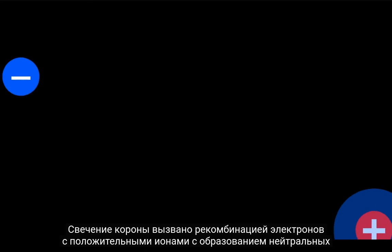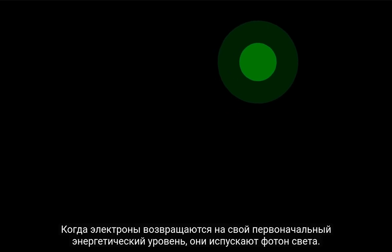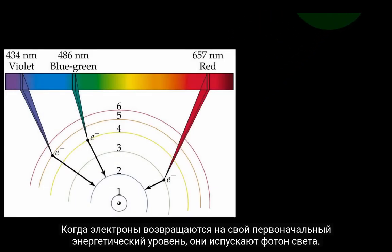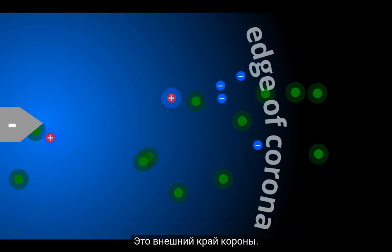The glow of the corona is caused by electrons recombining with positive ions to form neutral atoms. When electrons fall back to their original energy level, it releases a photon of light. At a certain distance from the electrode, the electric field becomes low enough that it no longer imparts enough energy to the electrons to ionize the atoms as they collide. This is the outer edge of the corona.